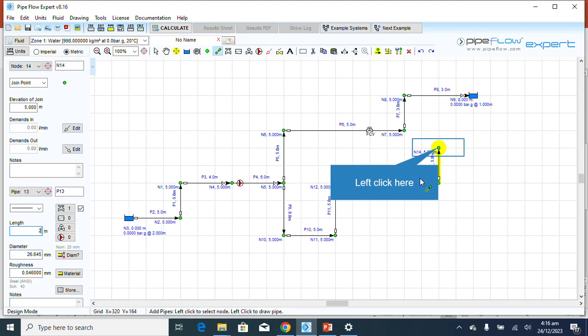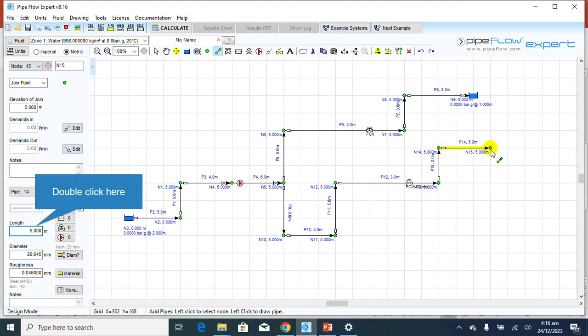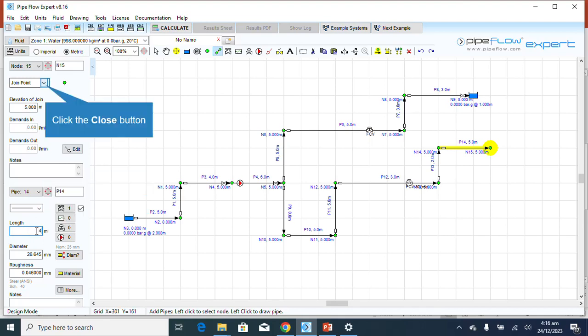Then there is a bend, a standard bend, okay? 2 meters of the same size, that is 25 millimeter nominal size. Okay, we're done with that. Now I'll add the next line from here to here, and the length of that line is 4 meters. So we'll just change this 5 to 4.